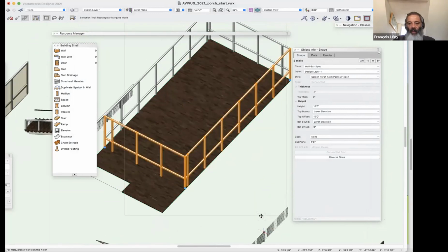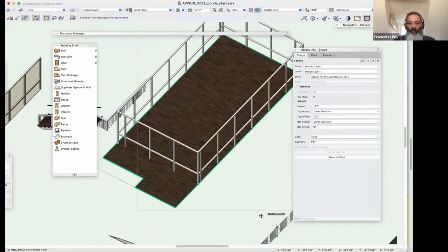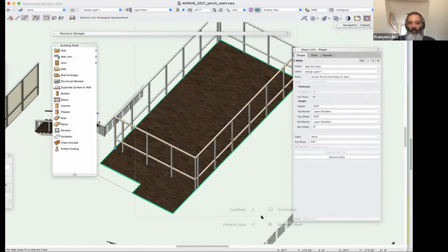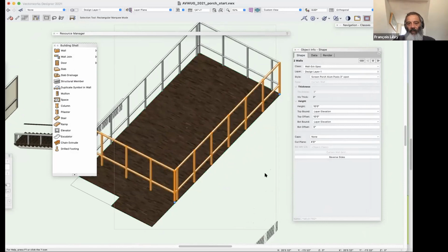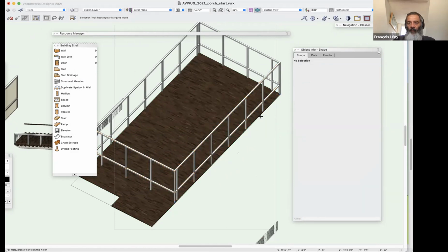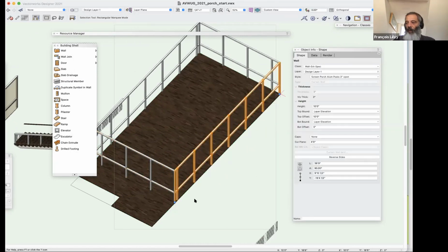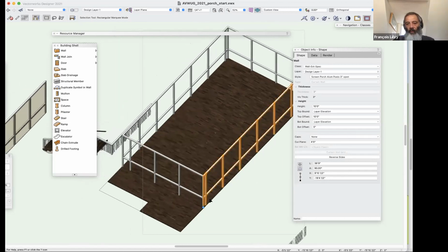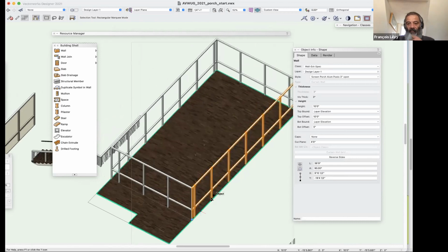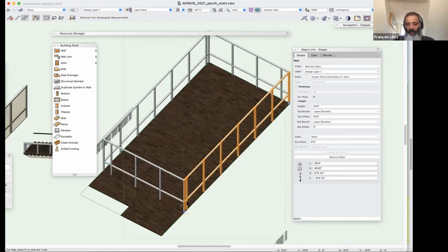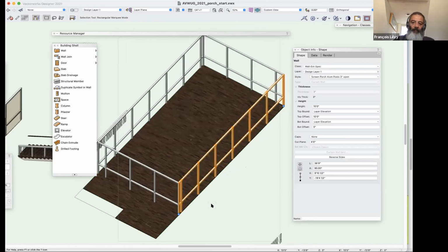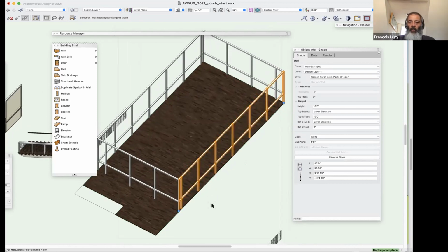And you can see that Vectorworks has very nicely laid them out just like I told it to at 6-foot centers. And that is really nice if my wall happens to fall on a 6-foot module, but it doesn't. So I'm going to need to distribute these posts so that they're evenly distributed, because there's no way I'm going to make somebody build this way.